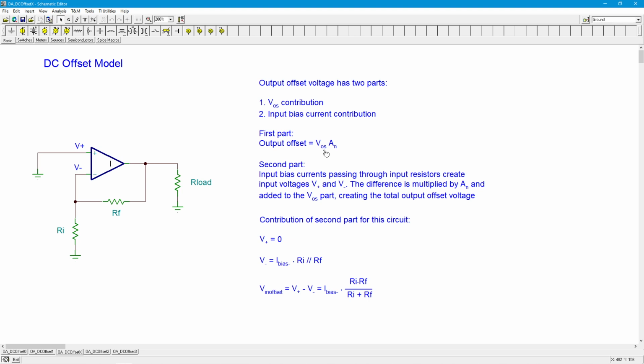So it could be 5 millivolts, it could be 0 if you're really lucky. It could be minus 4.3 millivolts, minus 0.2 millivolts, or plus 1.37 millivolts. You just don't know. Same thing is true with the input current offset. We don't know what the bias currents are precisely. These two bias currents coming in here, do you think they're going to be identical? No. Even if the emitter currents were identical, the betas for the two transistors most likely are not. So the base currents, in other words the input bias currents, are going to be slightly different. That's going to produce a little bit of an offset.